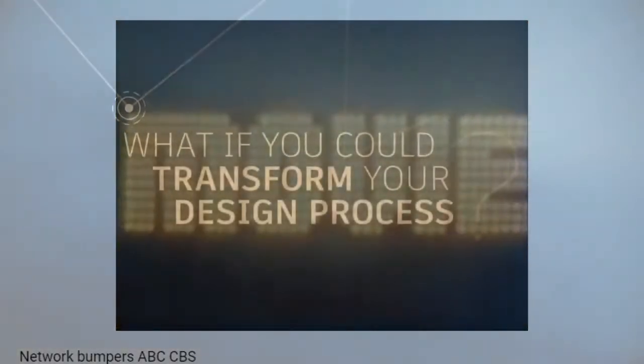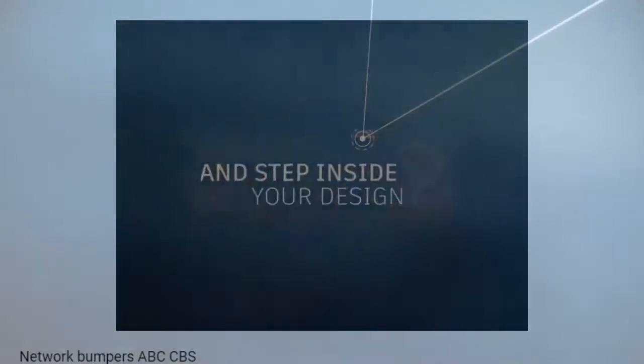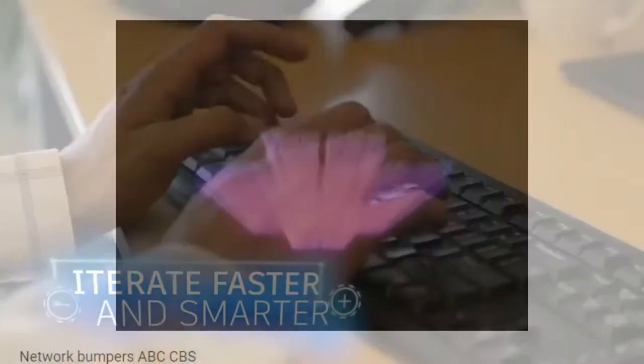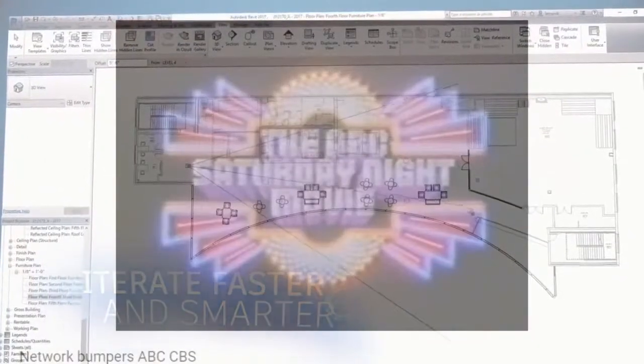Now, there's various ways to do this. If you cannot do that, just a slight depression, in place flush. Select the Architecture tab and Model in Place, choose the Floor category and create a void extrusion. We need a slab depression. Remember to use the Cut Geometry tool to cut the void from the floor before finishing the family. Alright, so let's just do that.